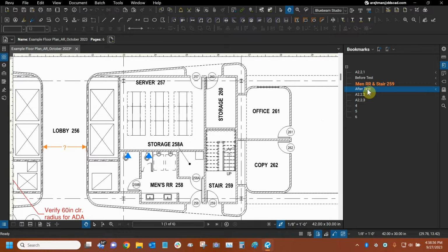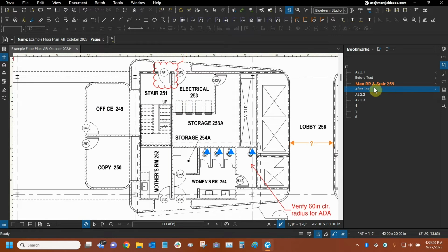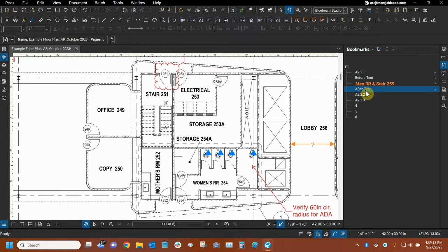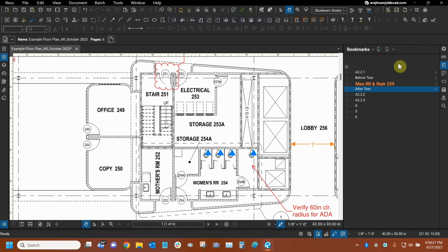Oh, it looks like actually it did not create the section in this area. And so what we can do now, after making this one, is we can just right-click on it after we navigate to the correct view and do set to current view. And that should fix it. Now let's test it. Back and forth we go. Perfect. That's much better. So that's essentially how this works.